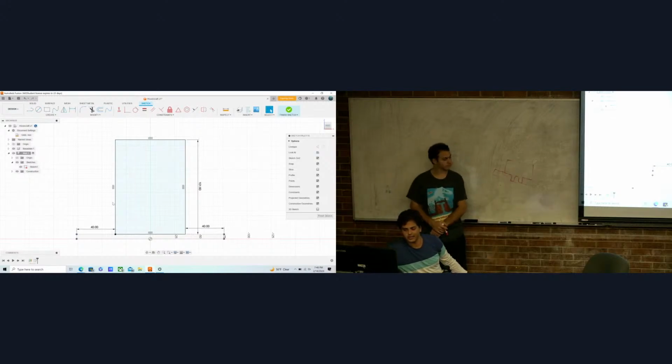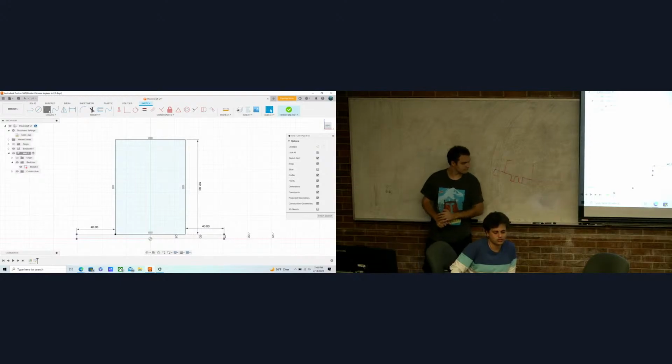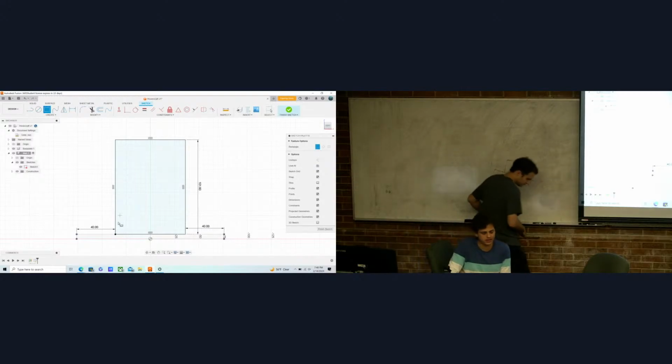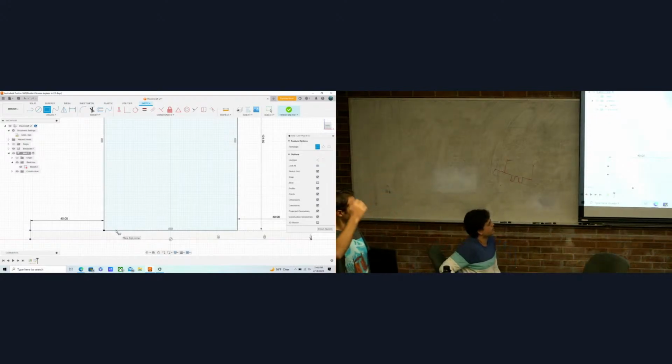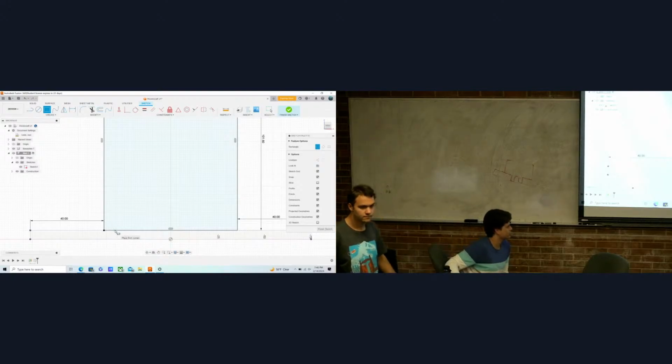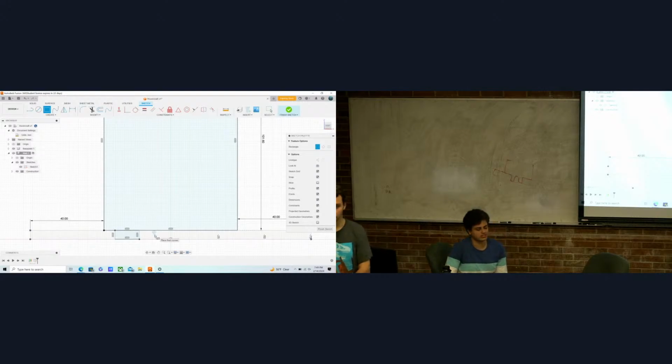So we'll go ahead and make some tabs. We'll use a 2-point rectangle, top left, to make that. I will go ahead and put one right here. So make sure that you're actually snapping. When you're snapping to 2 lines like this, you'll get a little X, but it's the same thing as the square we've been talking about before. It just means you snap. So we'll snap one corner to the bottom edge of that. We'll snap the other corner of the rectangle down here at the bottom. Don't worry about dimensions yet. Just make sure the top corner is snapped and the bottom right corner is snapped.